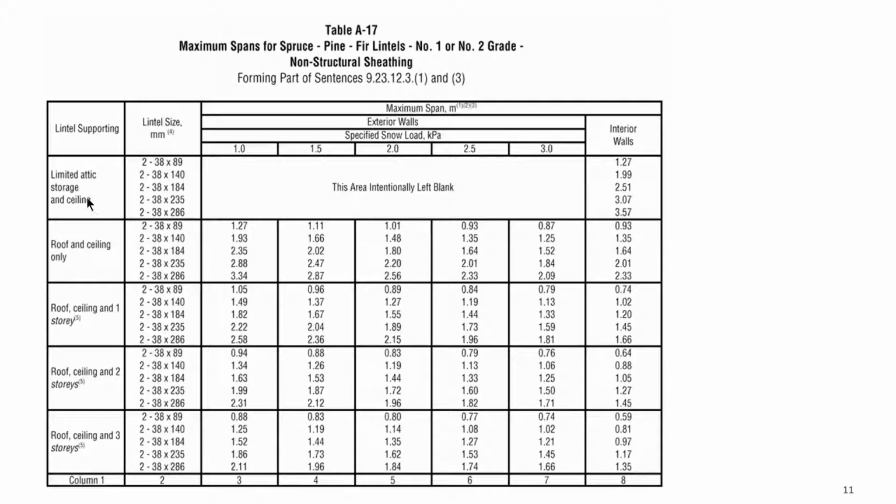So it's really based on what you are actually supporting, how many floors of weight you're supporting, and the snow loads. If, for example, you had this at 1, I would go to the next one, 1.5, and anything less than 1, I would go here, but 1.5. Remember, the building code is the minimum standard. If you go 1 step higher, that's not a bad thing. But from a building inspector's point of view and a building review point of view, they're looking at whether you met the minimum standard. So this is what this sets. You can always go more, you just can't go less.